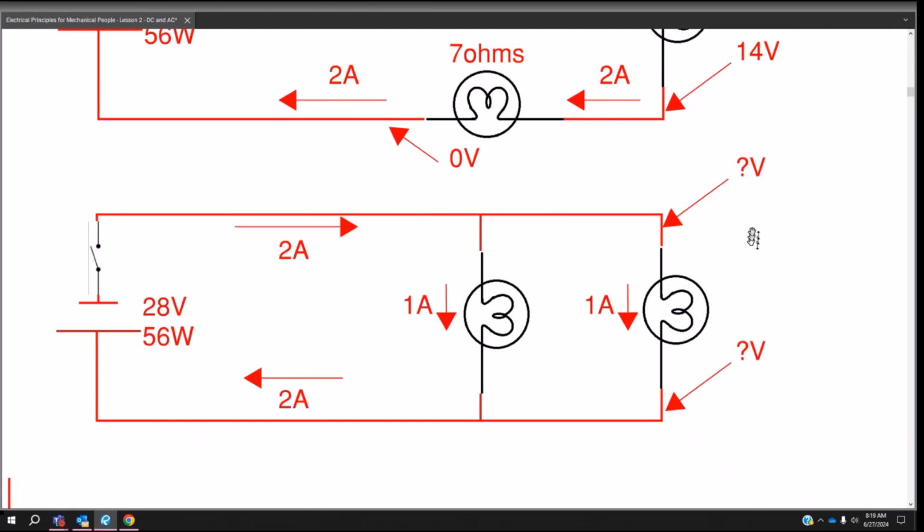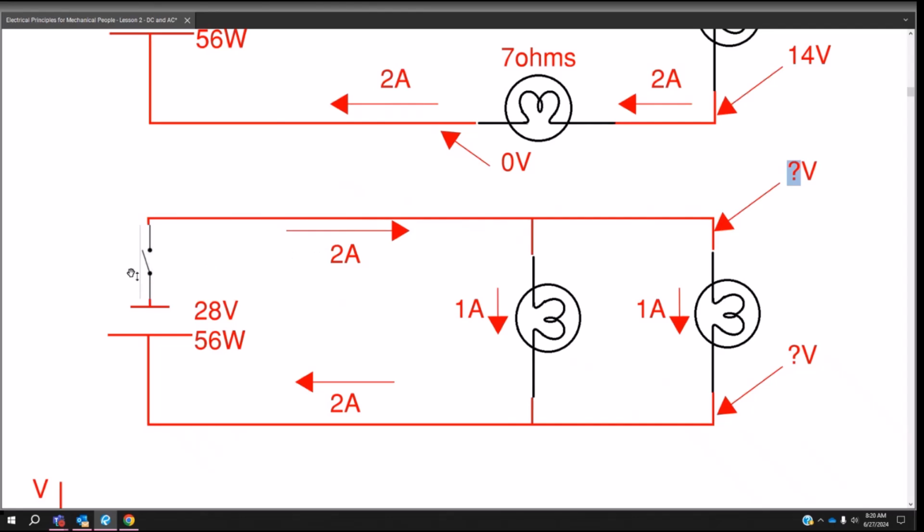Okay. Right? So on my voltage meter, if I put one here to the battery, what am I going to be reading? So if I were to put a multimeter touching this side of the battery and this side of the battery, what would I read? 28. 28 volts, yes. So electrically, since this is all conductor, there is essentially no difference than if I were to touch it here versus here on the battery itself. Which means it'd still be 28.